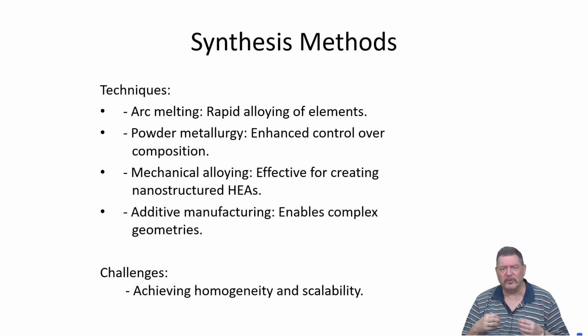And the same we find for these additively manufactured materials, which tells you that this type of processing involves very, very large strains. And if you think of it, it's basically a liquid-solid process, additive manufacturing, right? So locally you melt by an electron beam or by a laser beam your material, and then it solidifies, but you just do it in the geometrical features you like to have.